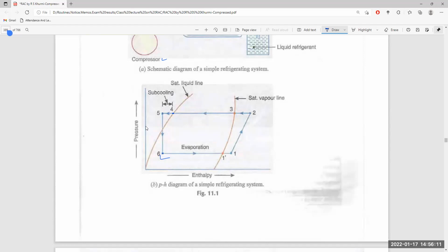is partially liquid and partially vapor, and it is converting to vapor state by absorbing the latent heat from the wall of the tubes, the wall of the refrigerant coil, as well as from the inside of the refrigerator, cooling the inside of the refrigerator by absorbing the heat from the coil, and then it goes back up to the point 1.